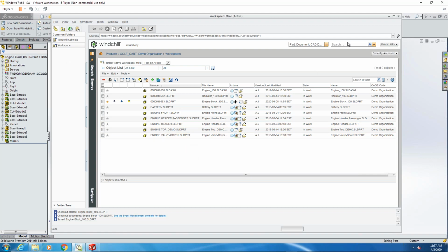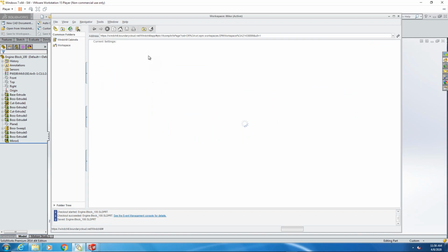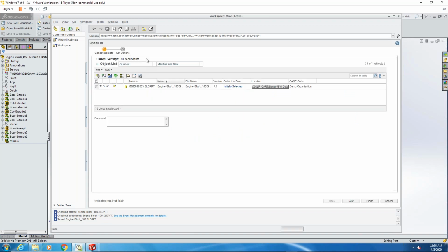All right, so at this point, I can go in and take this file and I can check it in. So I can take it and say, okay, I'm going to go ahead and check this file in. I'm just going to go through and now check this file into Windchill. Down here, I can make comments.